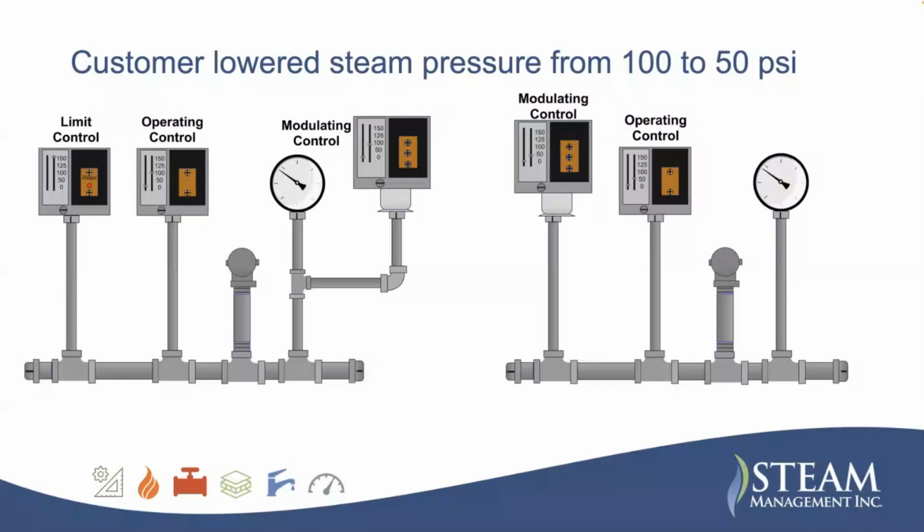Then you keep dropping it down, and you get down to 50 and say, oh my God, it's going crazy, we're getting carryover. So you say, okay, we're going to drop it to 60 psi instead of 50, and we can live with the way the boiler operates. That'd be the way I would do it. It's time consuming, but you're getting the best actual response from your boiler then.